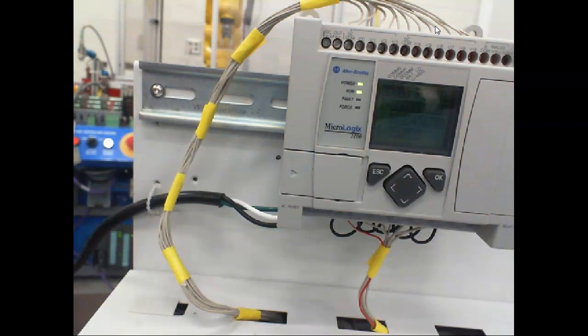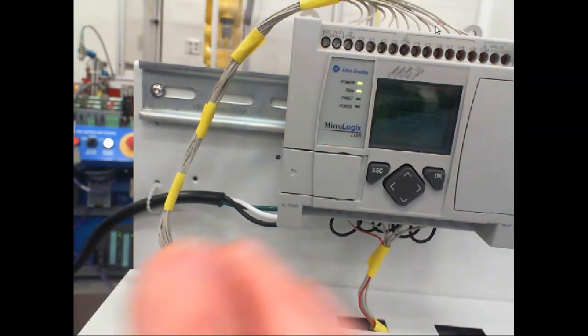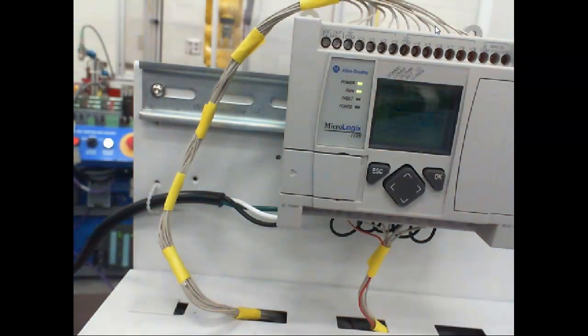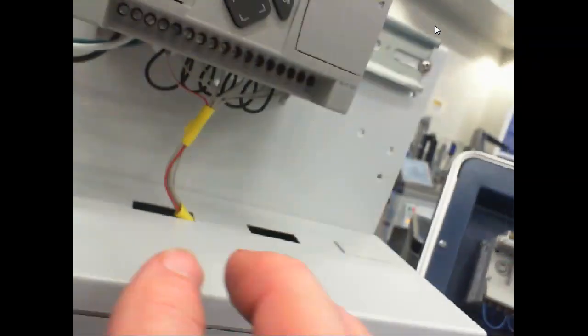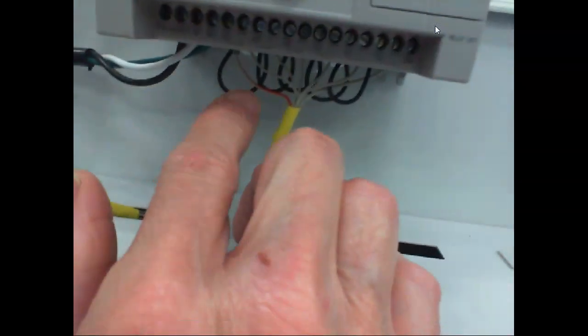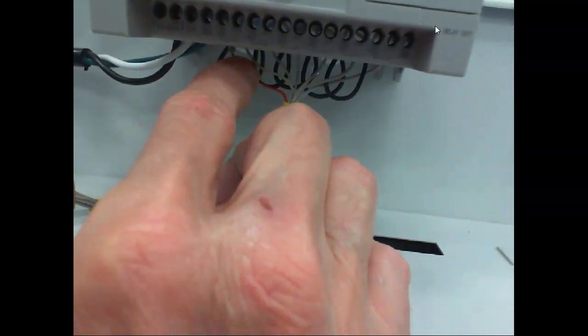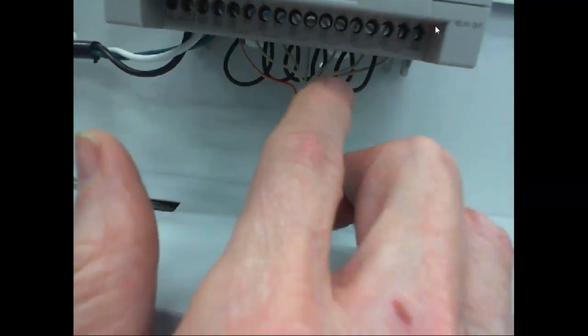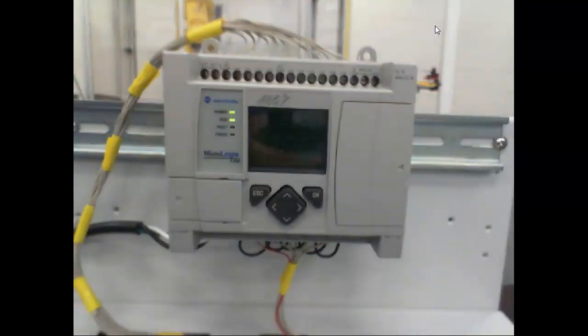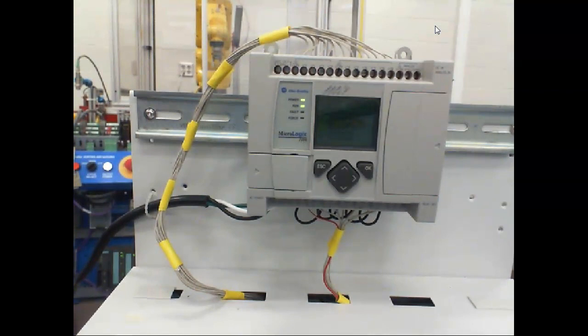So you'll buy a PLC with sinking inputs. And like I said, I'm not going to say you're going to run into that all over the place. Predominantly in the U.S., we run sinking input ports, and we run sourcing output ports. So if you look real close, you can see all these commons down here. And what I've done is, here's the plus, and I've jumped the plus to all the ports. So we have this PLC set up for sourcing outputs and sinking inputs.